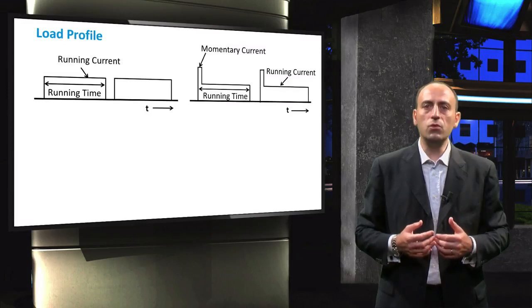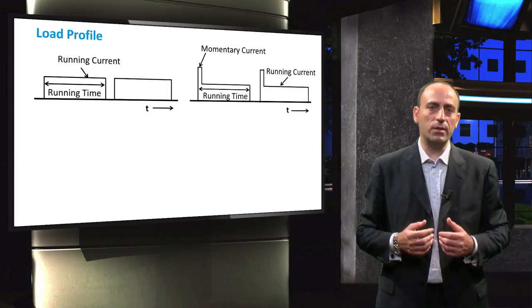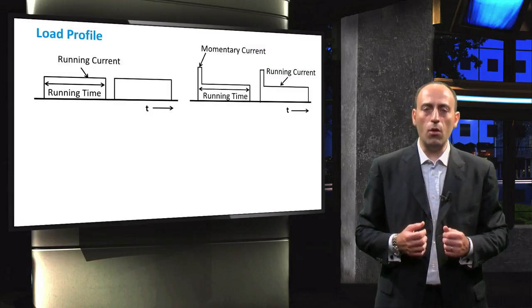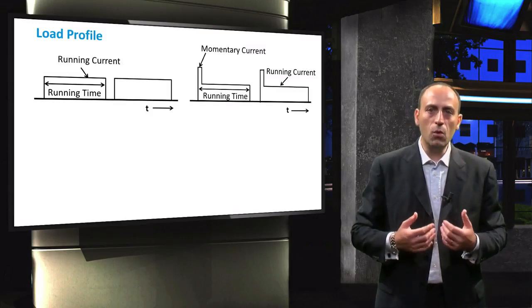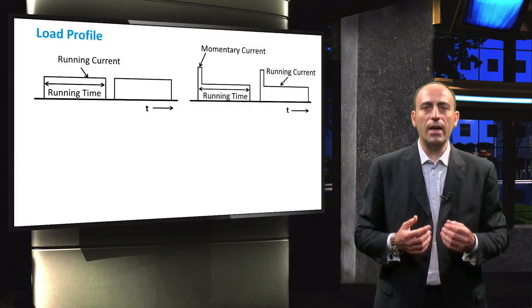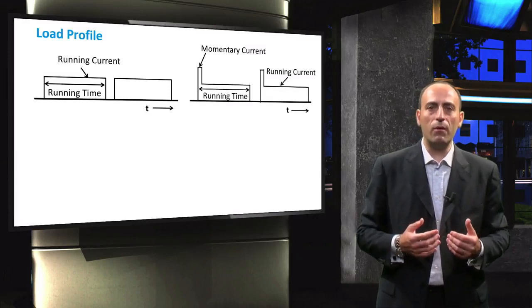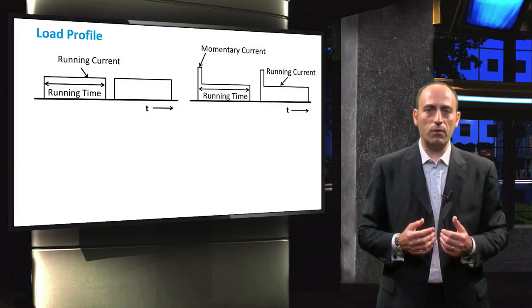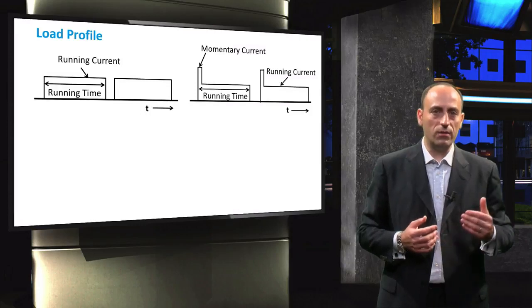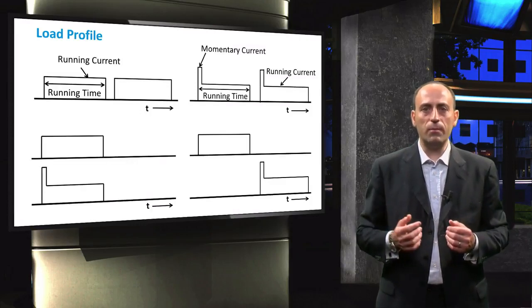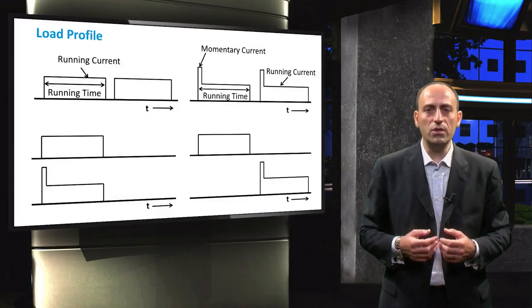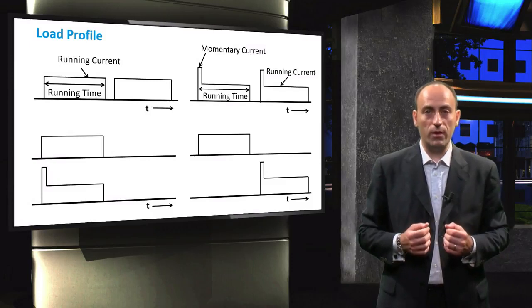However, many loads do not have a constant power consumption, but instead show momentary peaks during their operation. Such a peak generally occurs when the load is being switched on or off. In addition to knowing the load profiles of the different loads, it is also important to know their time of operation during the day. In a typical household, for example, there are various types of loads. These loads can operate at the same time or at different times during the day. So when analyzing the load profiles, we should also consider the time at which the different loads are operated.